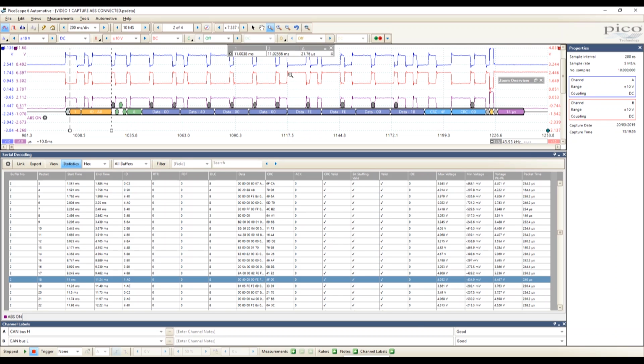So there are 11 bits within that ID, and the ID 1A0 equates to a message content priority. And if we were to think about ABS at this stage, because that's what we're dealing with, a message from the ABS ECU would be high priority, hence it's a low value, a low number. Whether that has come from the ABS or not, we're not 100% sure at this stage, but there are features that we can explore, and there are a number of things that we can do on the vehicle that hopefully will reveal that ID.